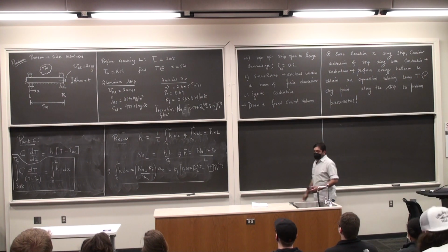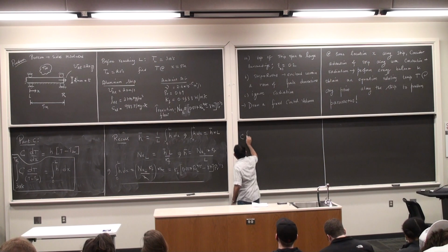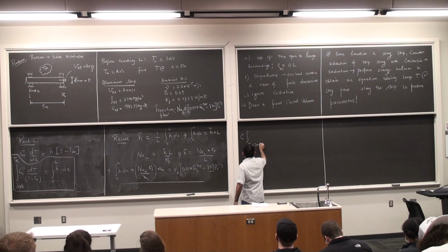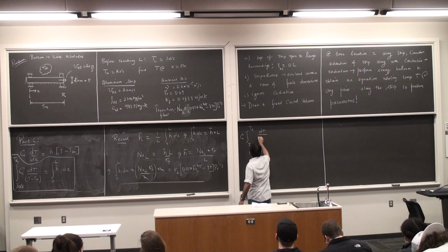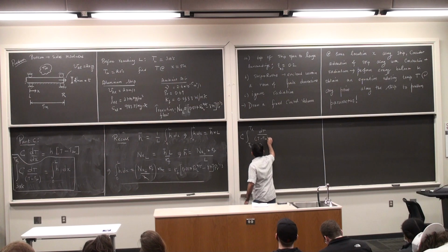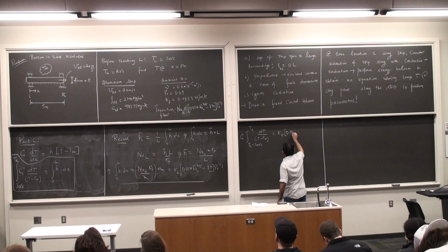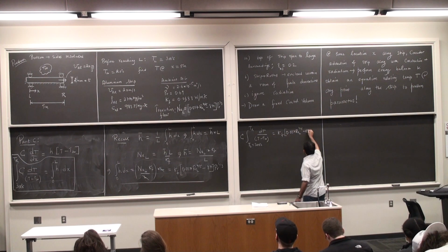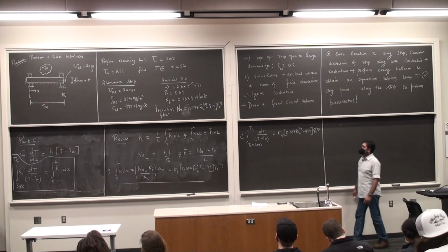I just have to substitute this back there. So integral constant, I'm going to call this as TL, which is 300 degrees Celsius, so dT by T minus T infinity is Kf times 0.037 Re_L to the 4/5 Pr to the power 1 by 3.